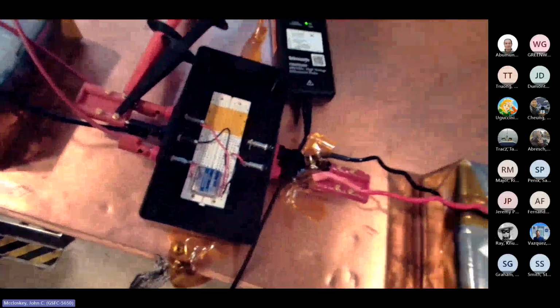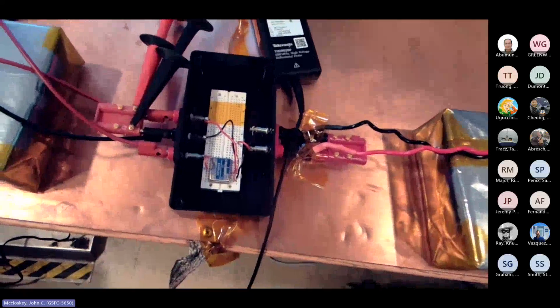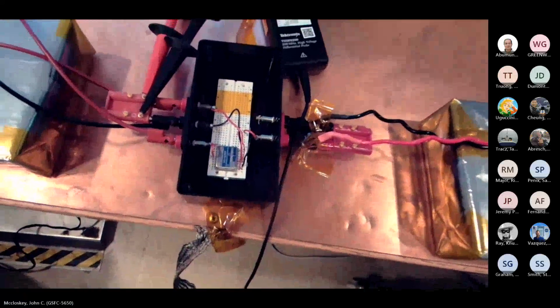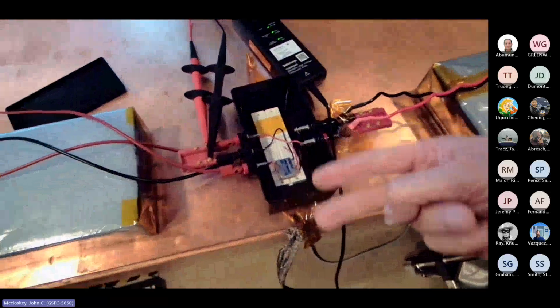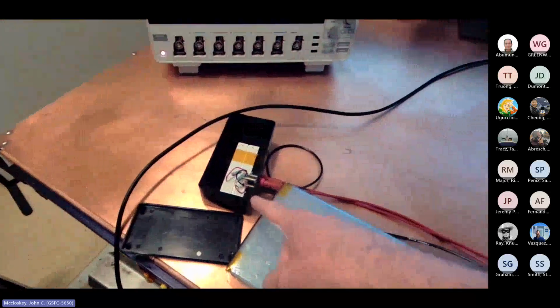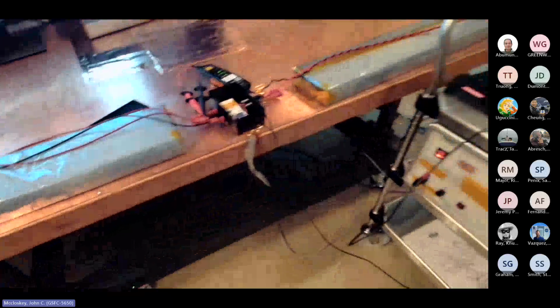This is the power converter that we use for our conducted emissions tests, so it's the same basic test article. It's bringing 28 volts in, giving you plus and minus 15 out, and then we go out to a pair of load resistors, because power converters don't like to be open circuited.